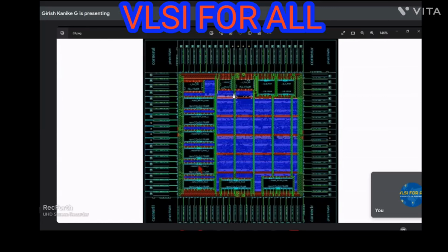It will be done in 3 stages, passes and legalization. In the first pass, you place standard cells inside the block, near the macros. Some standard cells communicate with certain macros, so they are placed nearby so that their connectivity length is not increased, which would again cause an issue such as crosstalk. In the second phase, the standard cells will be rearranged again near the macros, because the standard cells will shift from one G cell to another G cell.